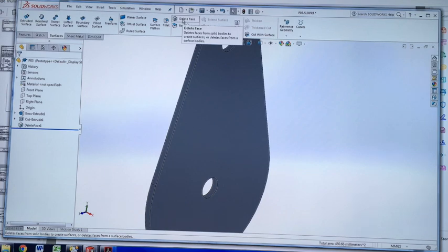With these parts we're making, is it alright if we save the prototype part for production as a completely separate thing, not as a configuration? What I would like you to do is not save it as a copy. The reason we do the configuration is so that it won't affect your drawings. So there's no need to save an extra file. You just press save here, and it'll still be fine, because all the changes we're doing are in a separate configuration.